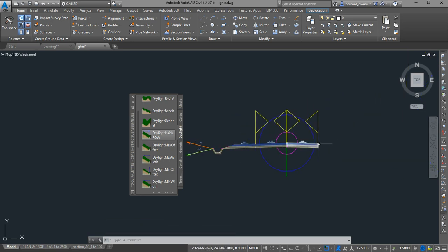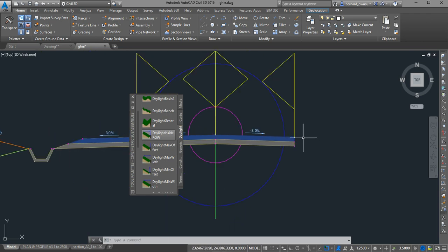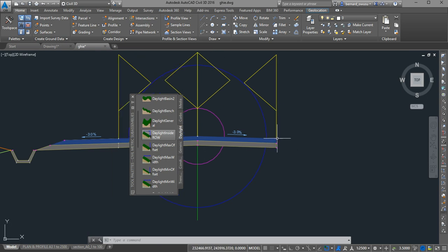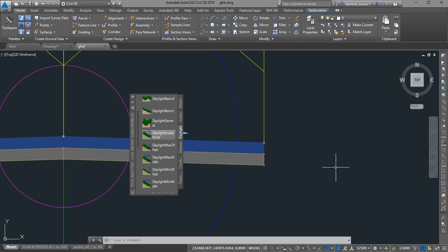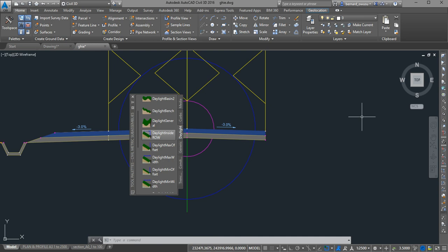We are going to the right. On the right, we'll be having a drain, but the drain is, let's say, under the walkway. So let's continue. We are having a drain somewhere here. So here we are going to have what? A curb, aren't we? We'll have a curb because it's going to be a raised walk. So we'll put a curb here, then we'll have our shoulder, then our walkway, then you may also have another curb at the end, then we'll have your side slope. Please, are we okay? So let's try and do it.